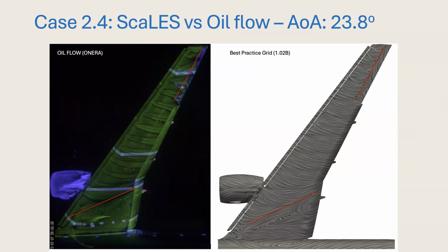I think the biggest thing is whether CFD can predict the outboard, those sizes of pizza slices, and then what is the size of this inboard separation? As I mentioned, there are a lot of factors for that, like the volume refinement and the chine vortex affecting it. If you don't have the right inboard outboard separation, then you really don't do well as a CFDer at predicting this. And this shows actually a very good comparison.